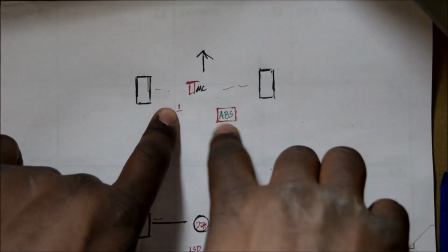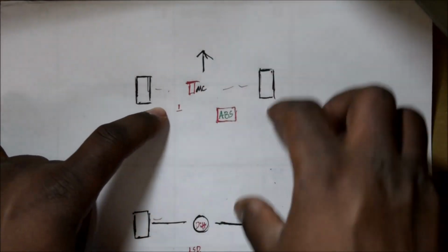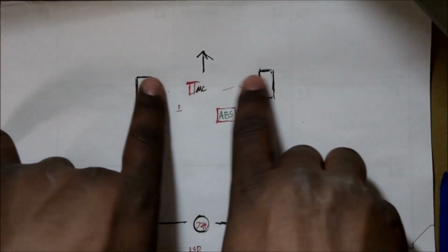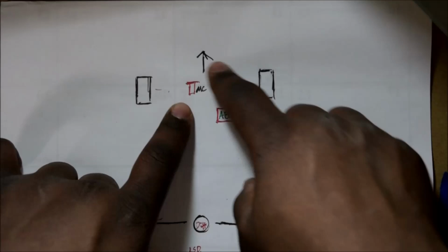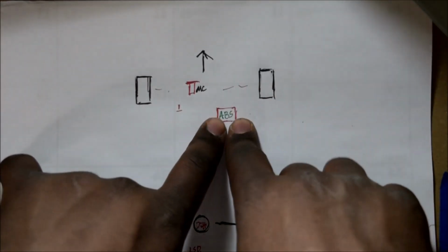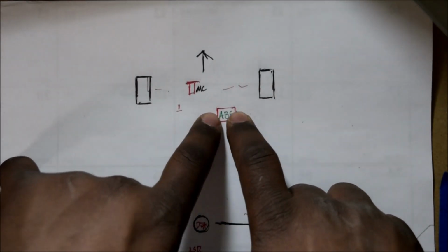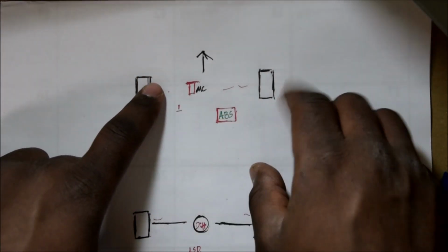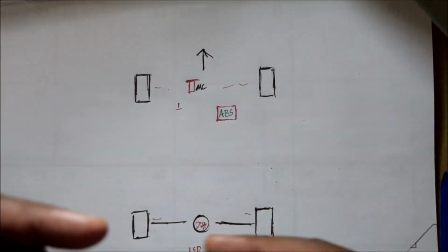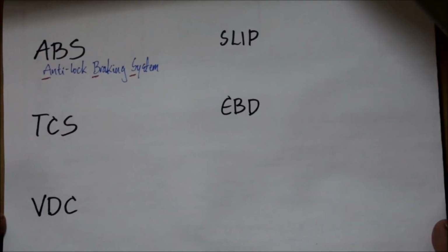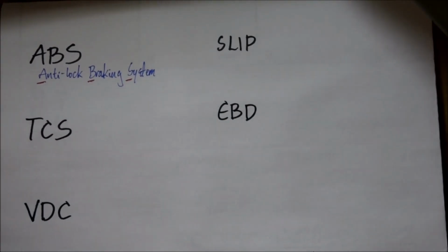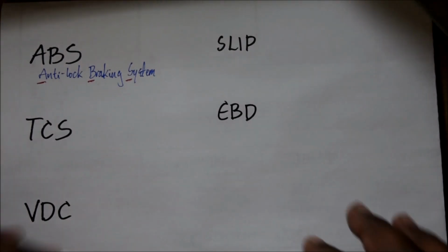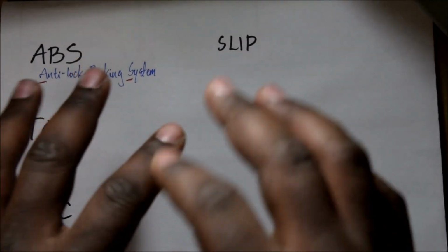Anyway, that basically gets signals from around the car, and those signals are sent to the ABS system, and then the ABS system modulates how much fluid goes in there. Basically, it puts fluid, releases, puts fluid, releases, and that's how it brakes and releases your car. So for the ABS, we talked about the anti-lock braking system, and during operation, as I said, it's a pulse, it's a catch